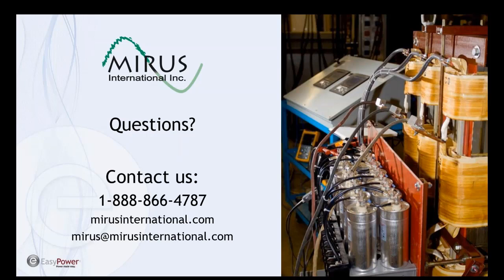So the question is about surge suppression. Can harmonics damage surge suppression devices, and how do we diagnose and fix that issue? Absolutely, harmonics can damage surge suppression devices, and actually surge suppression devices can resonate with harmonics on the power system. They often have capacitive elements in them. So it is something that you do need to concern yourself with. I'm not an SPD expert, and there are many different types. So I think it's best to address those issues with the suppliers of surge suppression devices.